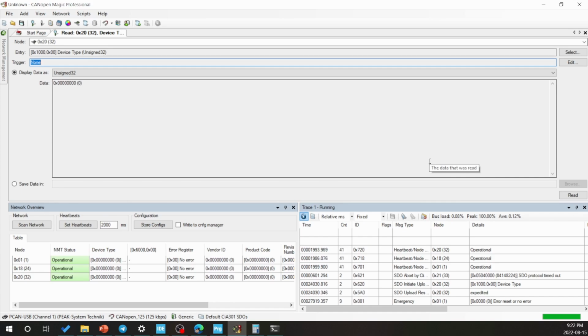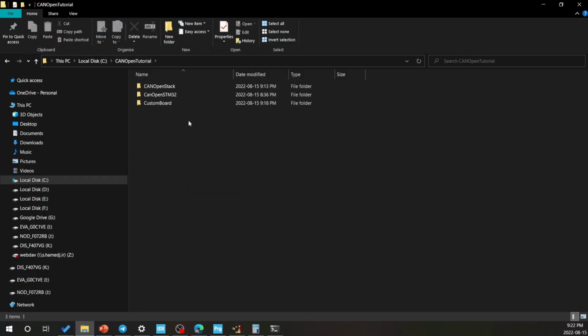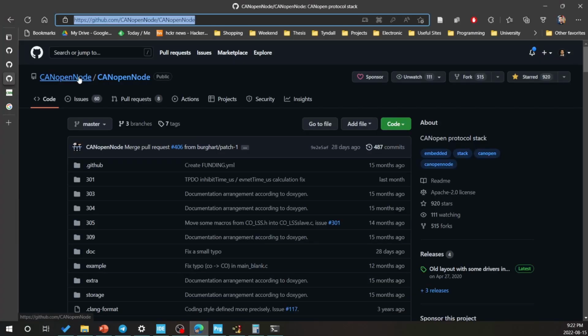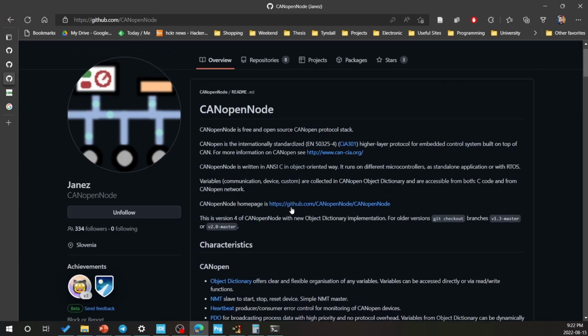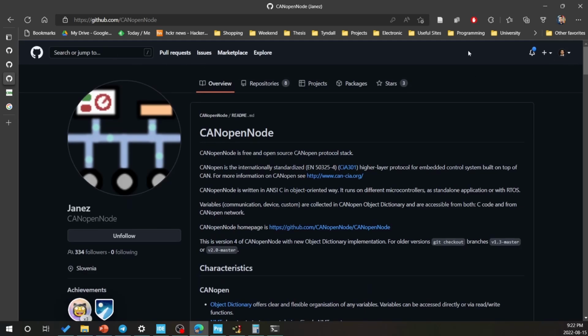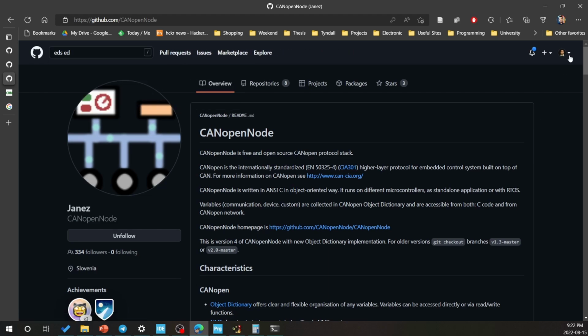Now let's start with the OD editor or EDS editor. So what I'm gonna do again, just come back here and let's go and find that OD editor. So again, I have a fork version of OD editor, or EDS editor, and I'm gonna use that one.